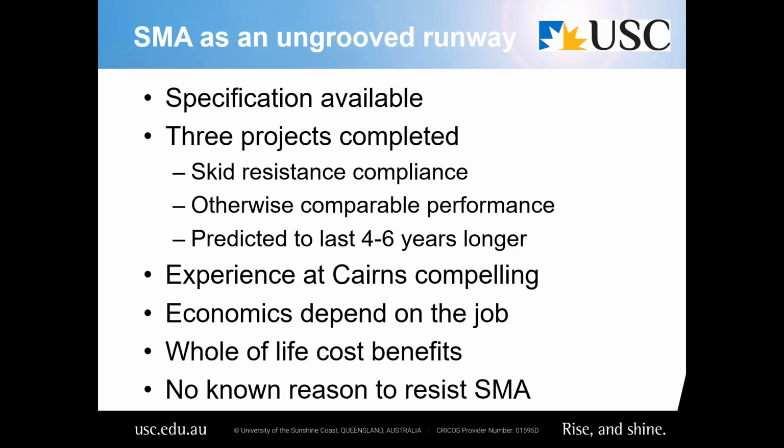The specification is now available. We've used it on 2 projects, and I'm sure there'll be more in the future. As I said, if you include the Latrobe experience, there's been 3 projects completed. Skid resistance is compliant on all 3 of them. We've observed comparable performance to the dense graded mix, and we're expecting it to last somewhere between, well, maybe 2 and 6 years longer, but we'll see how we go.